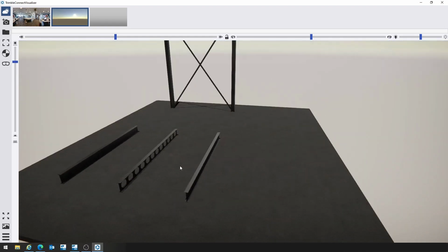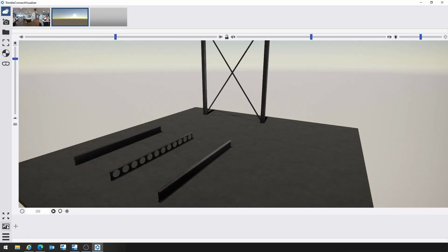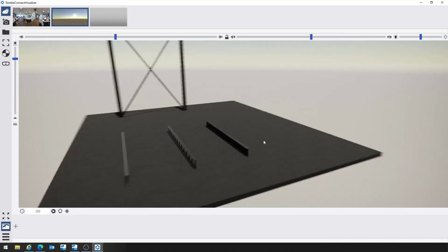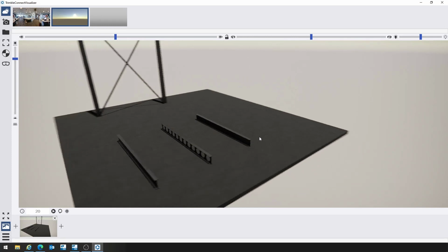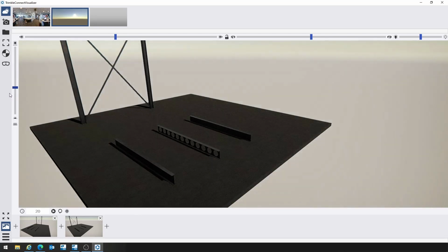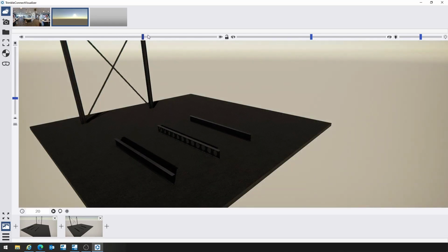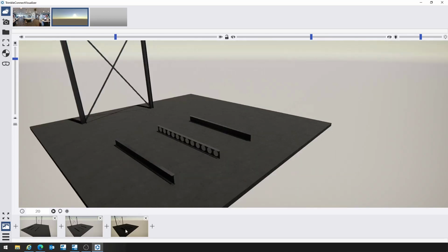So what we can do now is create a few screenshots using this screenshot button here in the bottom left hand corner. We're just positioning the view where we want it, and hitting the little plus symbol on the screenshot here. I can then rotate that around, hit the little plus symbol again, bring the shadows down and around, hit the plus symbol again, and if I double click on the first one, the second one or the third one, it will transition me to those separate images.